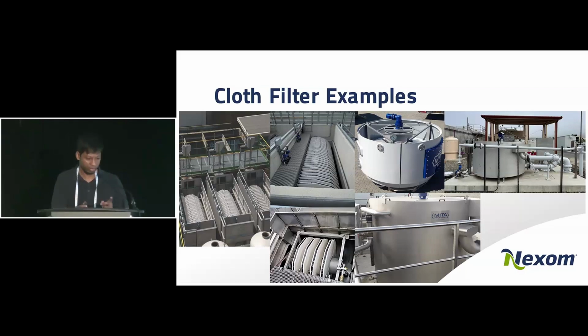If you look at the second picture from the left, you have a platform. Everything can be done from the platform, removing the disc or the backwash pump, the blue backwash pumps. On the right-hand side, you have a vertical orientation filter, and everything is done on the platform, on the concrete pad itself. We have a maintenance opening on the tank that you can access and change all the discs and components if needed.